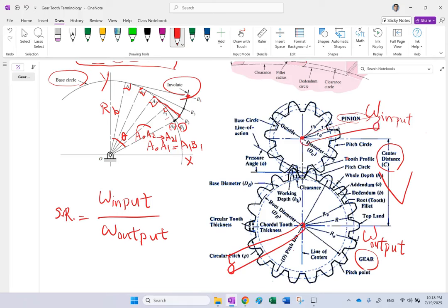If the distance between these two shafts is variable, because let's say the shafts are flexible, considerably flexible, and the points that the gears are mounted on are moving a little bit up and down, they have static deflection or dynamic deflection, then the teeth here are not going to be engaged very well with each other.